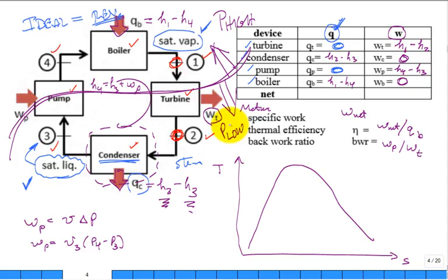What does a line of constant pressure look like on a TS diagram? That's right. So we go like this. I'm going to kick it over, up, come across, and then go up. And that's going to be P high. And then another line of constant pressure, go like this, go across, come up, and that's P low. Did I do that correctly? It's hopefully very important that you get this so that you could do it with a blank sheet of paper, and in your mind you work through problems on the exam. It's like, oh yeah, this helps me organize the information.